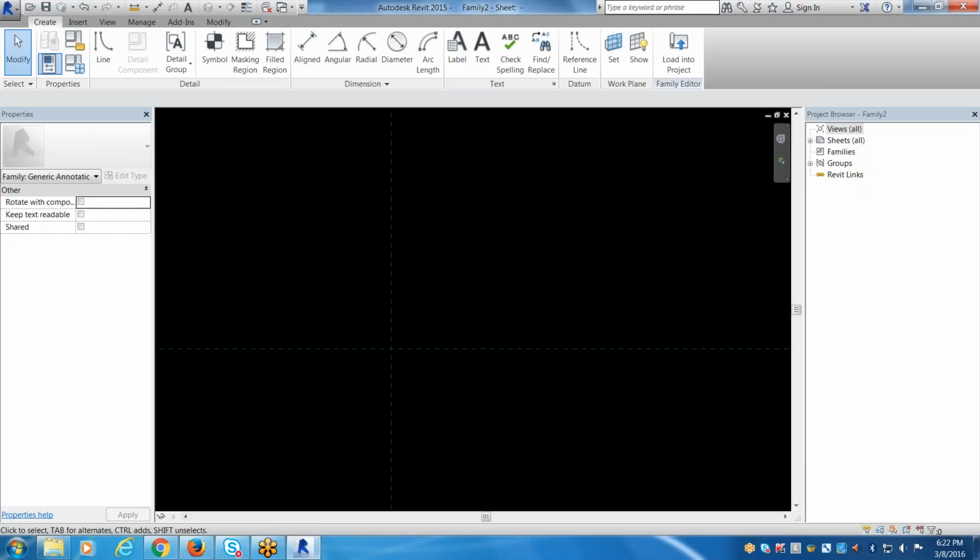Fine. How do we guarantee that? Because when we were making those sketches before, we were eyeballing everything. We gave no dimensions to it. I want it to be exactly that. So what we do is we create an additional, let's call it reference line, and set that reference line to 3/32, and then align our actual model lines to it. Okay?